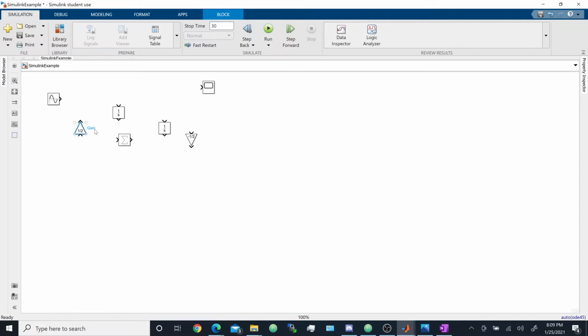That's kind of it. So again, if you want to make different parameters with all these, like here's our source. This is a sine wave, but if you wanted to change it to cosine, you could just double click it. Go in here, you can change the amplitude, you can change the frequency, the phase, and the phase is what you really want to change if you want to get a cosine. Okay, so right here, you can click right here, drag it over, that's our input.